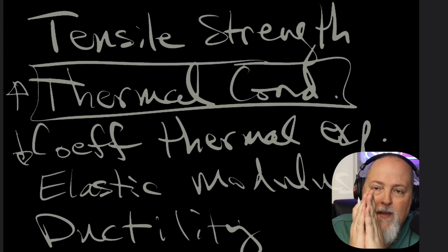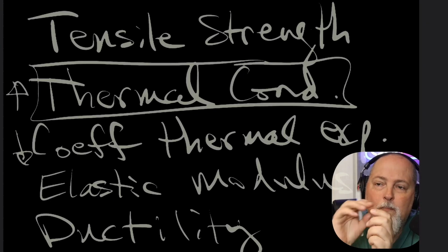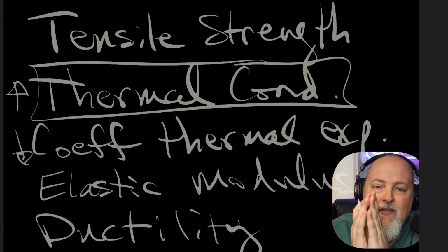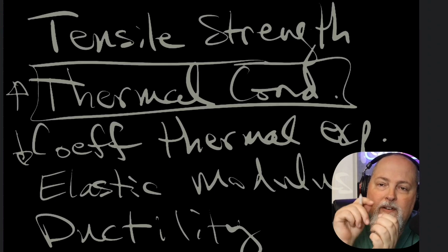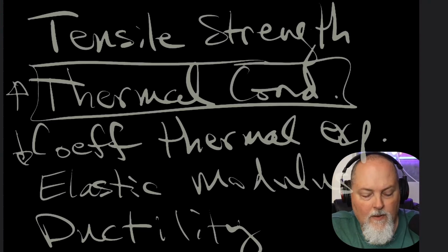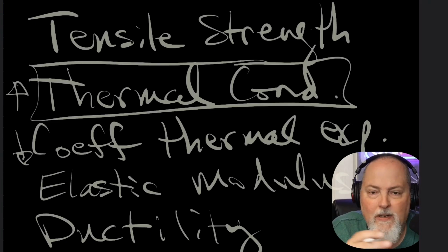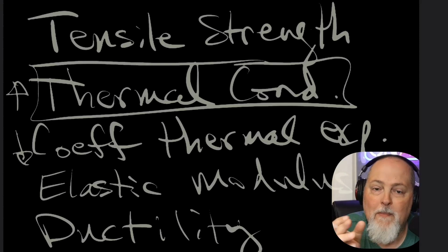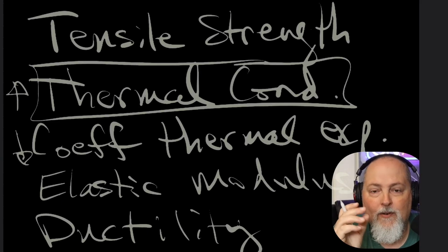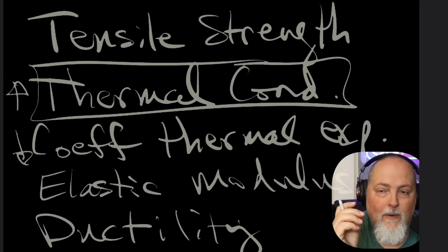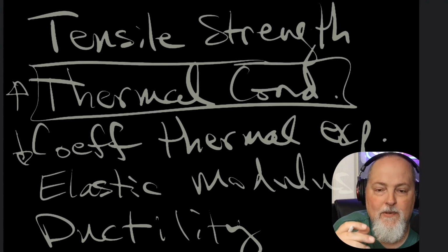And we solder them together, and then we put them in a little curl. And what happens is, as temperature changes, one metal expands more than the other, and it puts deflection on it. If it's in a coil, it tends to straighten out. And so that idea is that even across metals and different materials, there are low coefficients of thermal expansion and higher. And the low coefficient of thermal expansion is better because the inside surface of the reactor is not trying to expand as much with that temperature change.